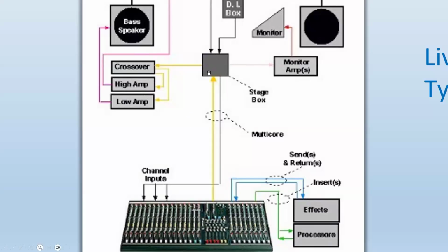So if you look at the resistance of the wire, if you have a snake that is 100 feet long, the resistance of the conductors in a specific channel could give you maybe 3 ohms, 5 ohms. Compared to 600, that is kind of negligible. So just keep that in mind.